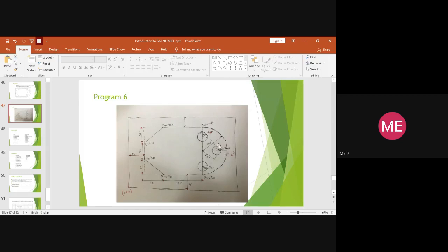For that you need to give the coordinate system, right? Here it was 225, and now the tool is moving in the horizontal direction by a distance of 30, because the radius here is 30. Here also it will be 30, here also 30, here also 30. So it was 225, plus 30 mm you will add. So it becomes x255. The coordinate of x changes from 225 to x255. Okay. So this is about the x coordinate.